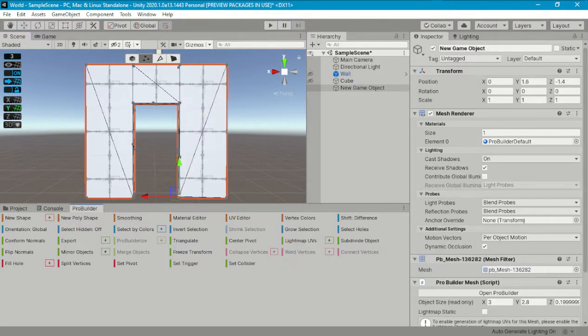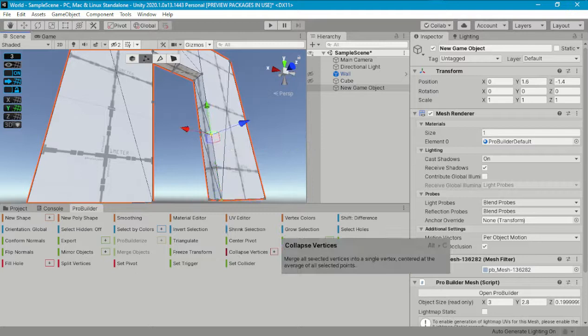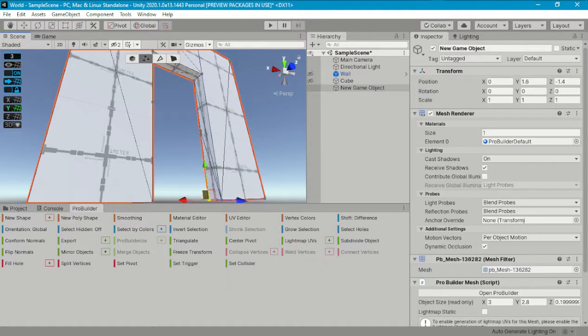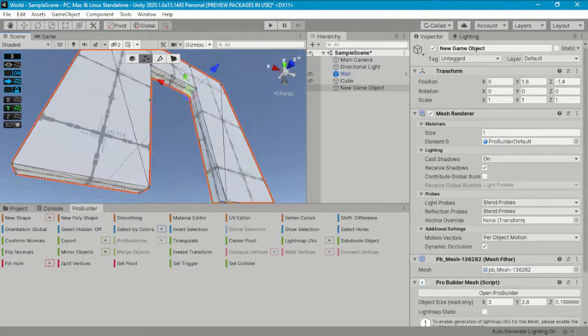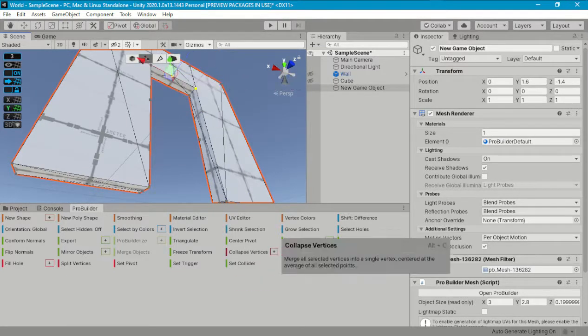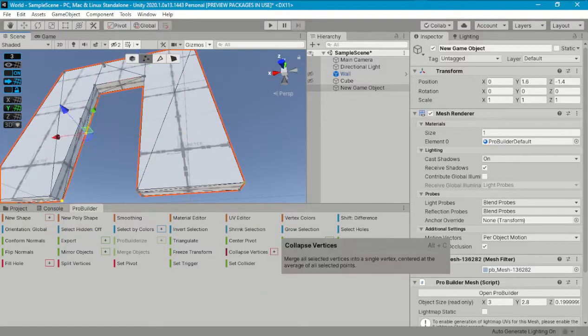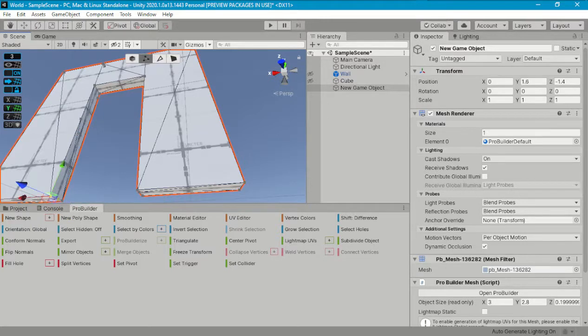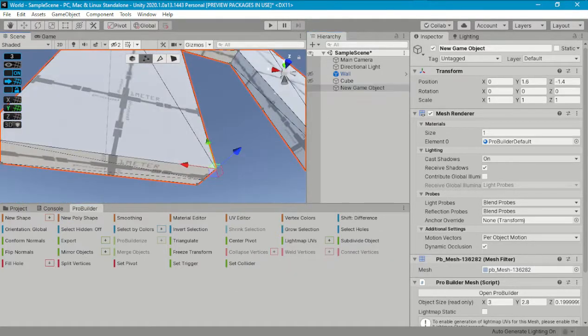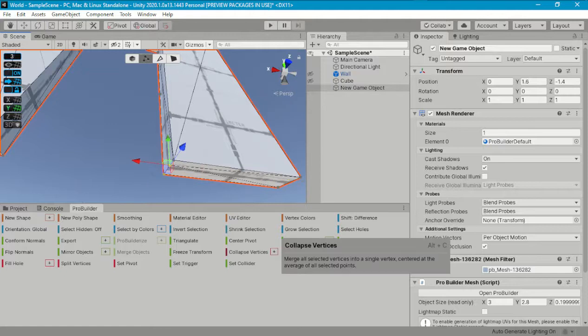We also have to do the same on the interior faces. Sometimes it's tricky to click on the right vertices. Orbit or pan the camera if needed. Currently, the Boolean tool is in experimental phase. As you can see, at this moment the algorithm generates a lot of unnecessary triangles. Hopefully, when released, we won't have to do all this extra work. But that is something yet to be seen, so, for now, you need to use it carefully.